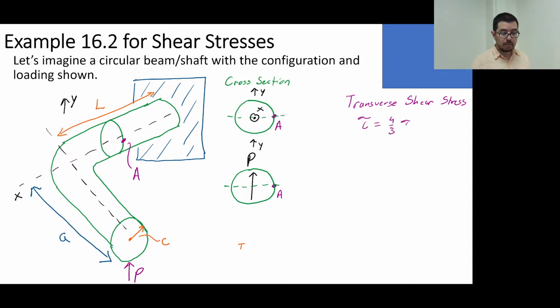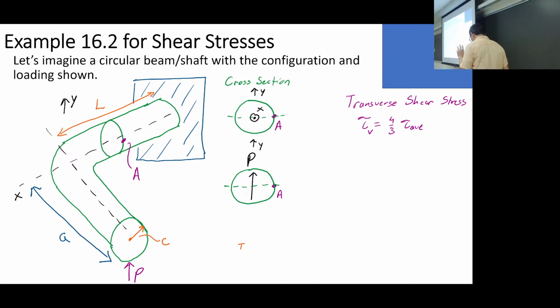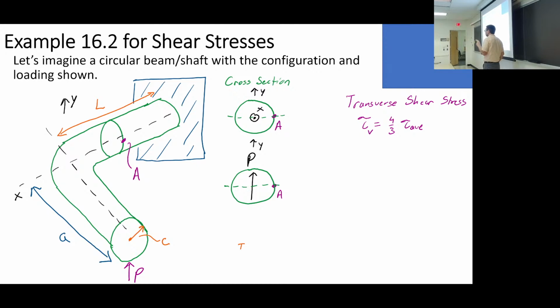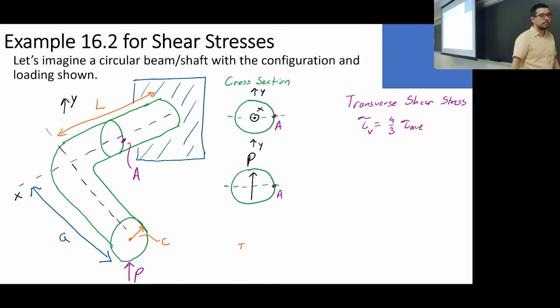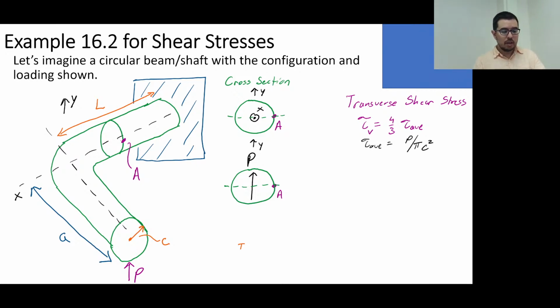Okay. So does that mean you have to do 3 separate equations? So, the number of equations maybe is questionable, but there are 2 quantities. I've got a quantity from the P being the internal shear force, and we've got this other quantity, which is going to be giving us the shear from the torque. So what do we have? We have a shear stress, from the tau average, from P being essentially like a fictional P here that's acting up.